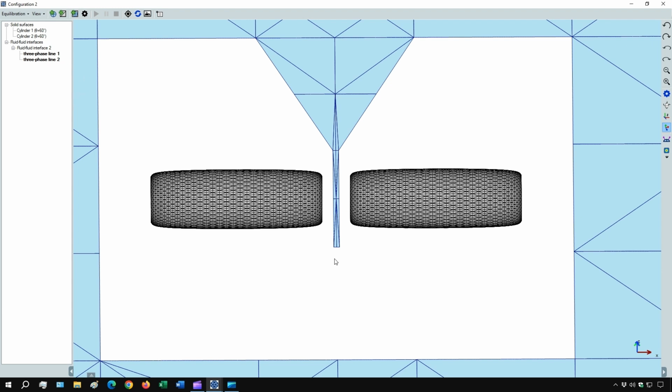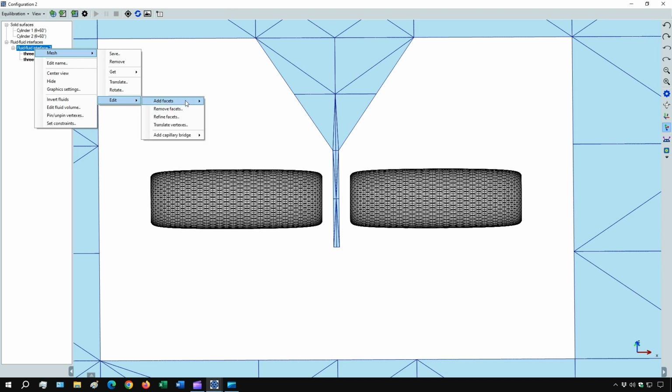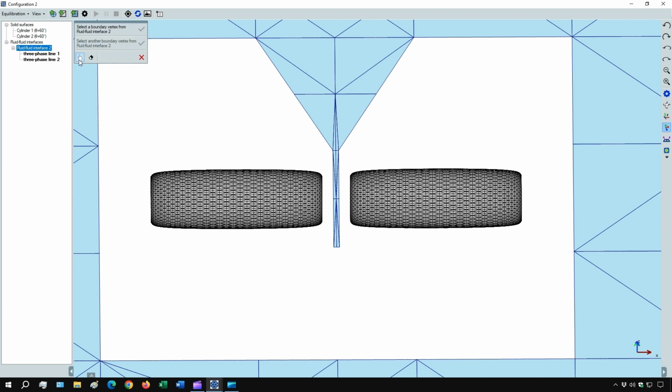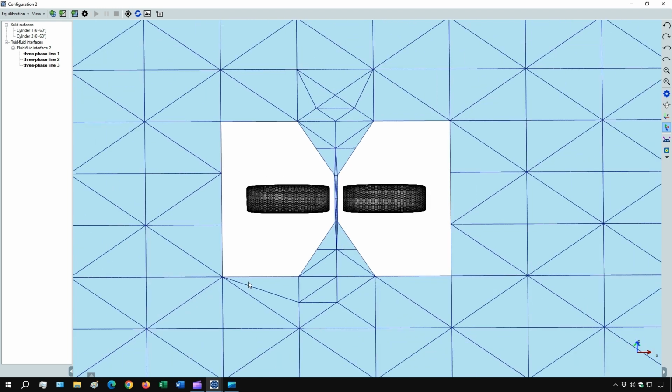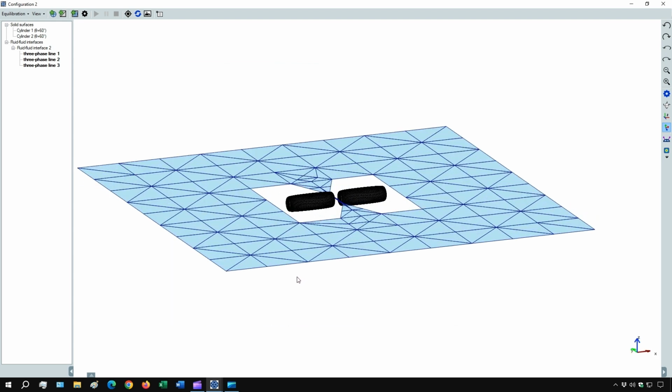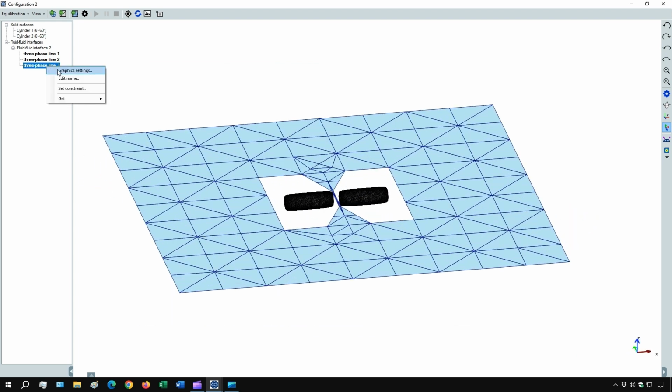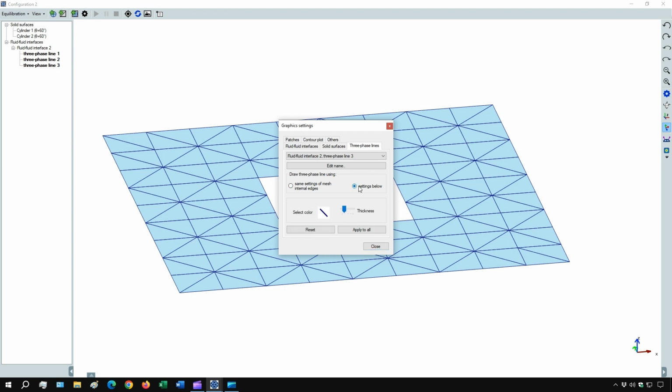We only need to connect these boundaries to complete the desired topology. For doing this, we select the Add Facets tool of the mesh, and then we click by connecting boundaries. This tool works like the previous one. That is, we select the two boundary vertexes where we want to make the connection. And then we click Confirm. We have now created a fluid interface mesh with the desired topology. Let's edit the names of its boundaries to remember which one is which.